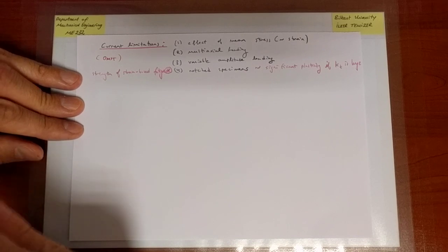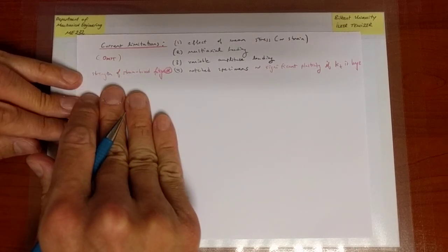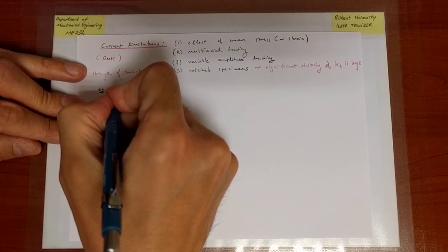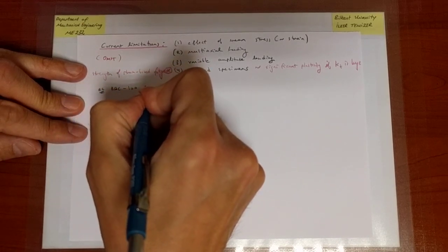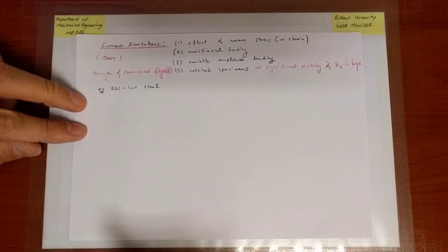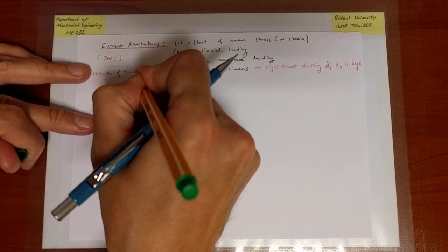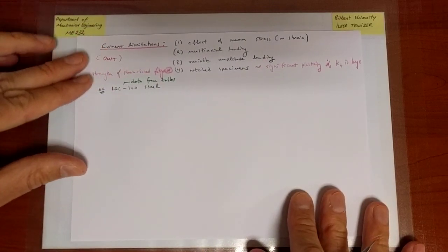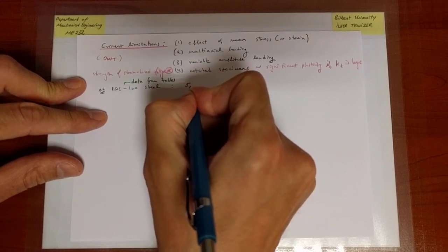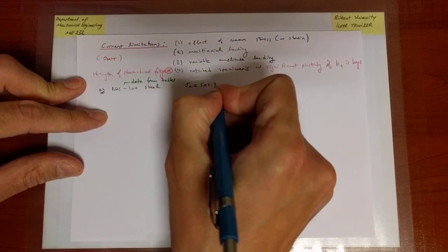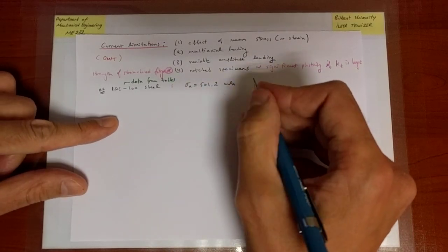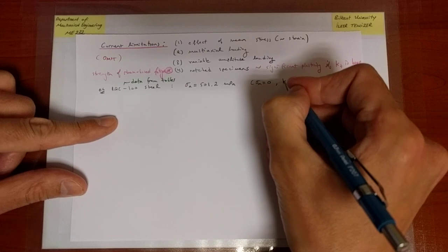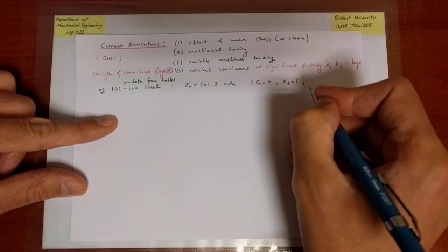So let us proceed, therefore, and demonstrate the strain-based approach as we've discussed this so far in the context of a simple example. And this is going to be an example where we take, again, RQC 100 steel. Remember that just like in all the previous cases, we will collect the data from the tables that are provided in our book. And what is given to us is that the stress amplitude is prescribed, 501.2 MPa. The mean stress is equal to 0, and so that's what we've assumed so far. And KT is equal to 1. In other words, we are dealing with unnotched specimens.